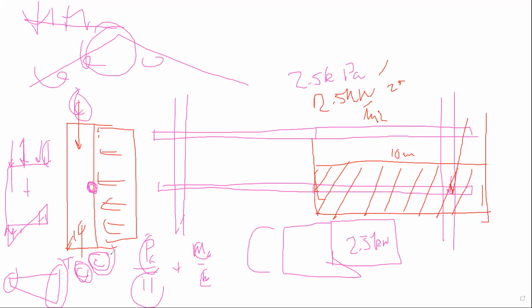Some people have difficulty seeing it that way, understand? But those are the actual stresses. This is caused by the axial load, and this is caused by the bending moment, understand? And that's how the textbooks tend to show it. But you have to understand that the compression here, well, those two add up. That's all you have to remember. And that's what this does.